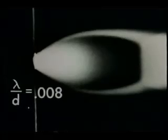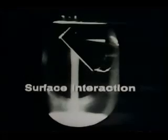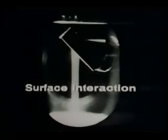In free molecule flow, the nature of collisions between gas molecules and solid surfaces and the resulting reflections are very important. For example, for bodies such as our washer, we need to state how gas molecules are re-emitted after they hit a solid wall when we calculate the aerodynamic forces or heat transfer. We can use molecular beams to learn something of how molecules scatter from surfaces.